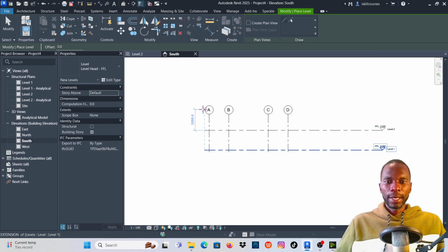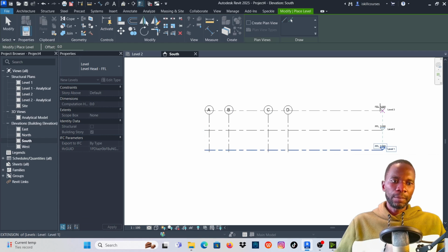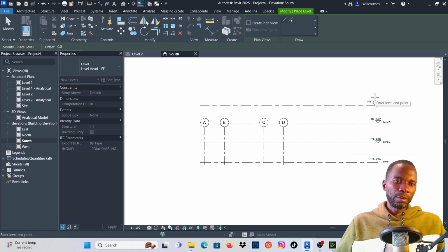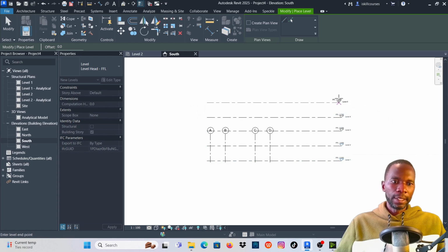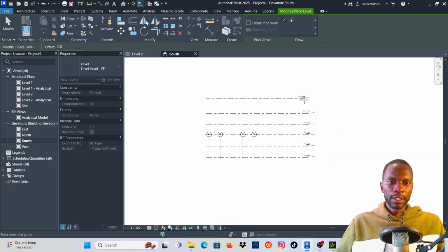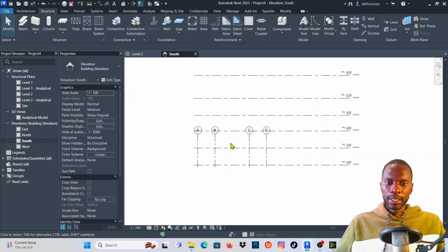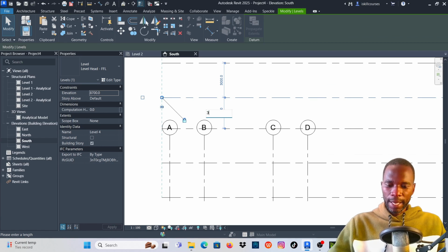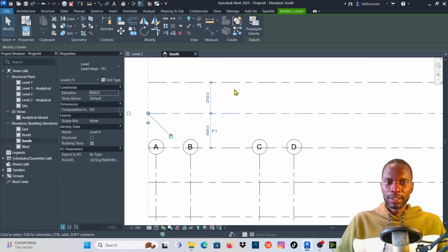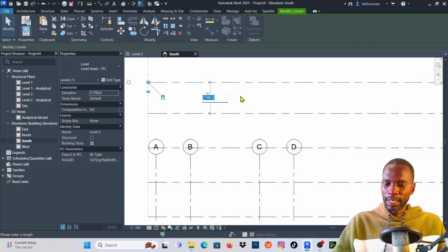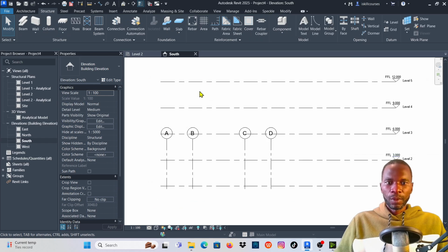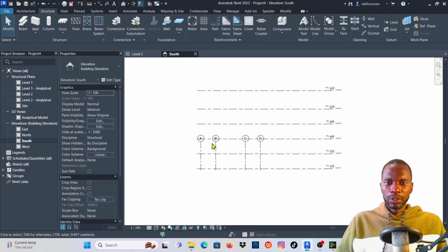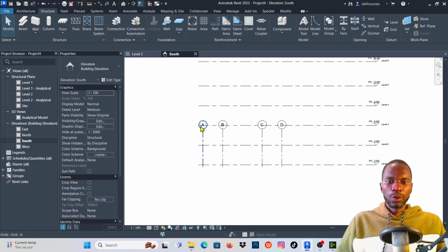If you want to have another one at 3 meters, you can watch the dimension and snap there. We have this one. And again, you can do that, but if you want to be fast, you can just place those at random and modify it later on if you want. Then click on modify. So the first two are okay. So the second one, just click the top one, then type 3M. Revit is intelligent to know that you are dealing with millimeters. 3M and enter. How many do we have? We have up to level 6, and this is what I want. I'm good.